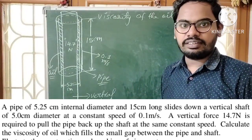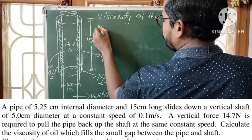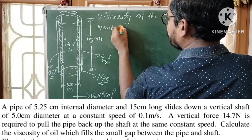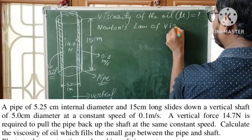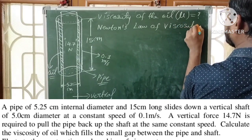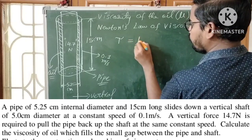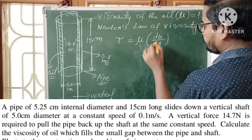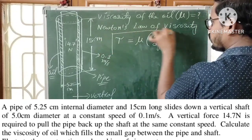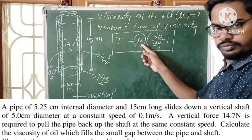So here the concept is viscosity of fluids. According to Newton's law of viscosity, shear stress is equal to mu into du by dy. So using Newton's law of viscosity, we can find viscosity of oil, mu.